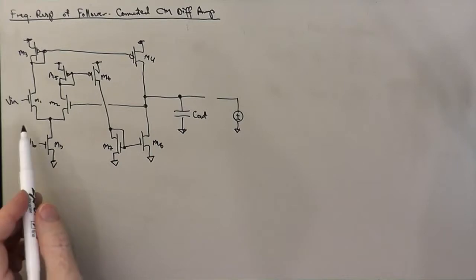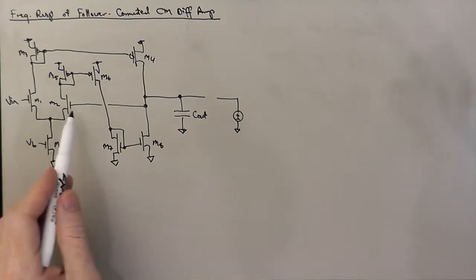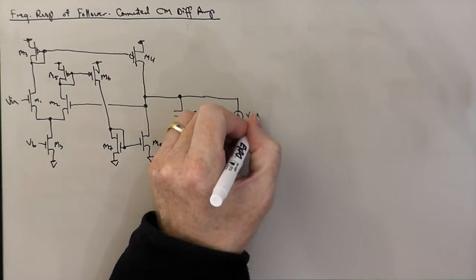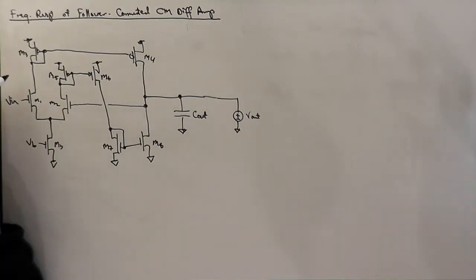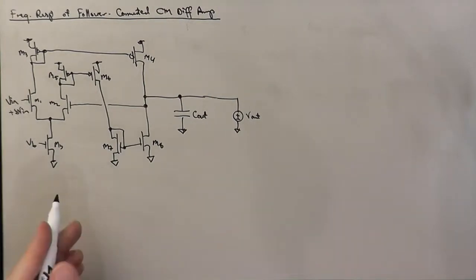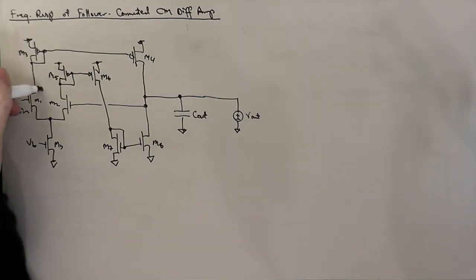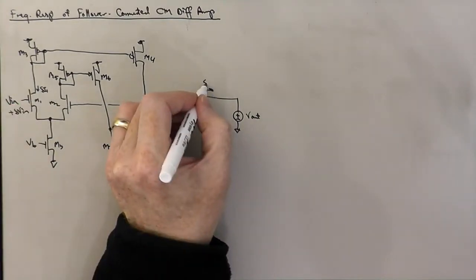And notice that is basically the common mode condition that we were talking about last time, where the two are basically balanced. And so V out is being held fixed at basically V in. And what we're going to do is calculate the transconductance gain of the circuit if we apply a delta V in to our input on top of some DC level. Well, that's going to give rise to a delta I1. I guess I should say we're interested again in the delta I out that flows out of the circuit.